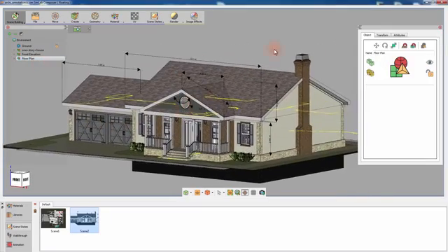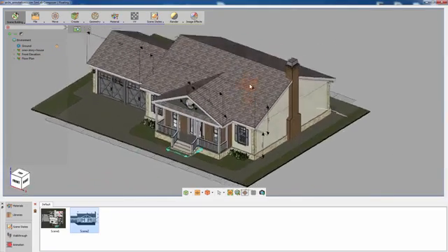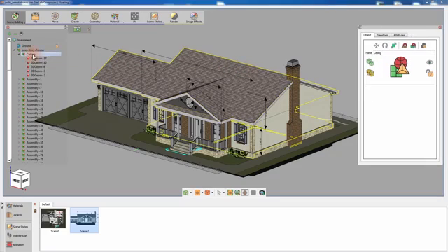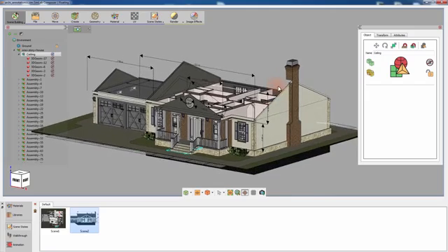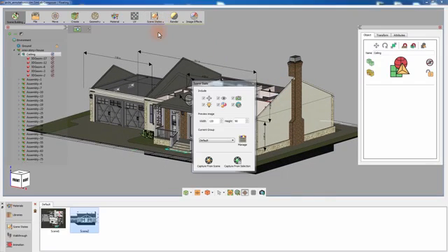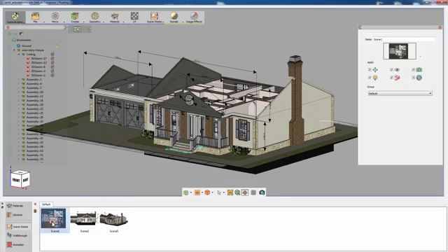Reveal all the objects and annotations in the scene and set the camera to a perspective view and click Capture from Scene to create a third scene state. Click on the first scene state and from the Attributes panel to the right, rename it to Top. Select the second scene state and name it Front. And name the third scene state Perspective.